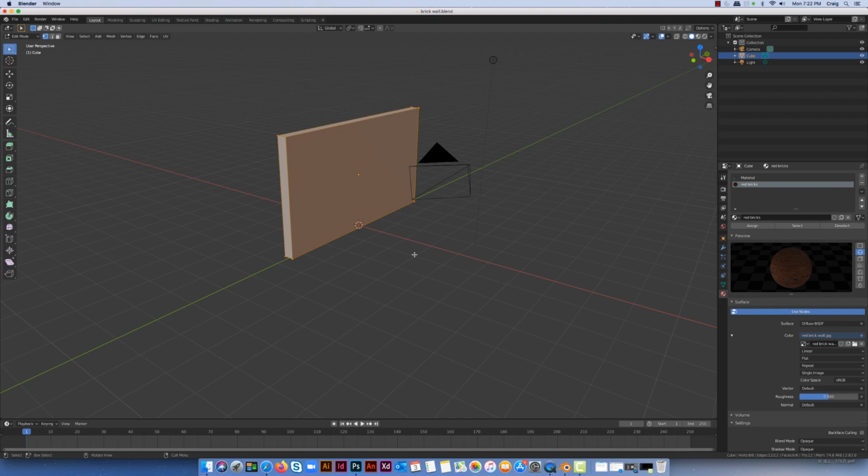And what I'm going to need to do to correct that is do a thing called UV unwrapping, which is to separate out all the parts of the object here which is selected and define them to the bricks. Now I could do the same thing by choosing one face at a time, but in this case I'll just apply it to the whole object, which will mean that you'll understand the concept that I'm talking about. So with the object selected, I'm going to make sure red bricks is on and click assign, and that will apply it to it.